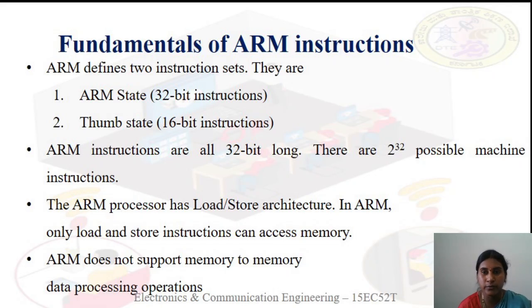Compared to other microcontrollers or processors, our ARM has special characteristics. Firstly, our ARM is highly pipelined. Do you know what pipelining means, my dear students? Pipelining means executing the instructions in parallel. While executing one instruction, our ARM processor will be doing some task with another instruction. Since you are executing in parallel, the performance of the processor will be much faster compared to other processors.